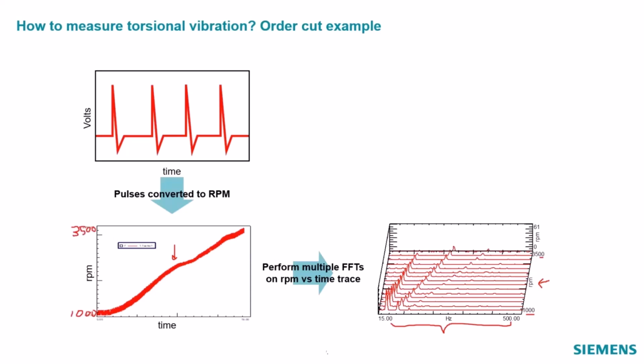And then the FFT of this data, this is not vibration and acceleration or sound. This is RPM. You get RPM over here, which is the amplitude of the RPM fluctuation. Notice that this is a lot less. That's 61 RPM as opposed to this one, which is 3,500 RPM. This is how much that RPM is varying around the main RPM.